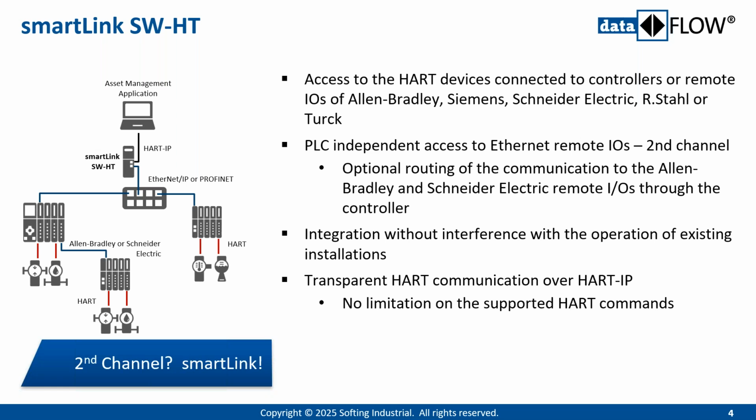There's no restriction on which kind of HART commands could be sent from the asset management application, because for the communication, the SmartLink SWHT is using the HART IP protocol. So that's a variant of the HART protocol, which is running on a standard Ethernet TCP/IP stack. And so therefore, the asset management application decides which commands it has to send to the HART devices, and the HART devices will get exactly these commands, then being sent via HART from the CFU or the remote IOs.